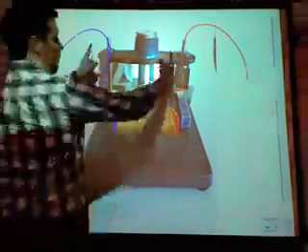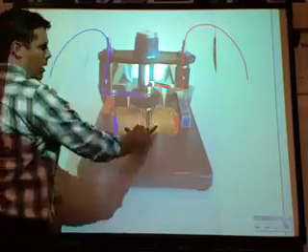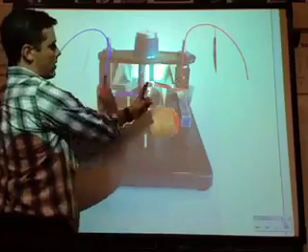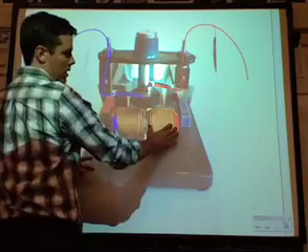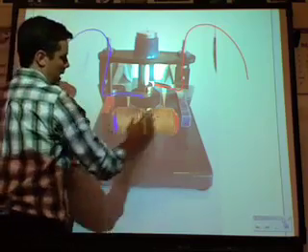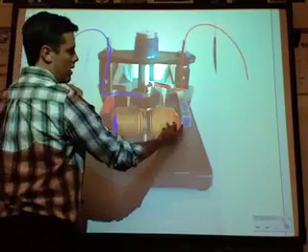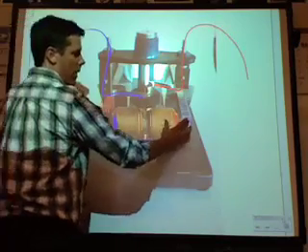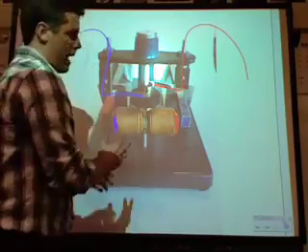Let's see how we're able to switch the wires on this particular coil. Remember, by switching the wires, we also switch the poles. As you can tell right now, these two poles would repel and these two would attract. If I switch the wires and the blue comes over here and the red comes over here, then they would be repelled and repelled. So I can change what's happening on any given end.